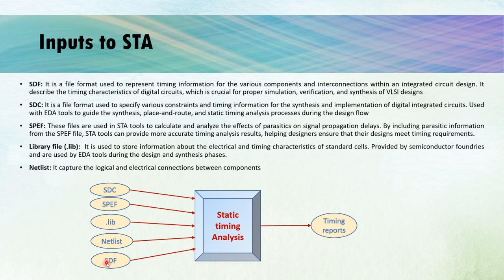Next is the SPEF file. SPEF stands for Standard Parasitic Exchange Format. As the name suggests, it is the file which has information about the parasitics of the circuit. SPEF files are basically used by the STA tools to calculate and analyze the effect of parasitics on the signal propagation delays. By including this parasitic information from the SPEF files, STA tools can provide more accurate timing analysis results and help designers to ensure that their design will meet the timing requirements.